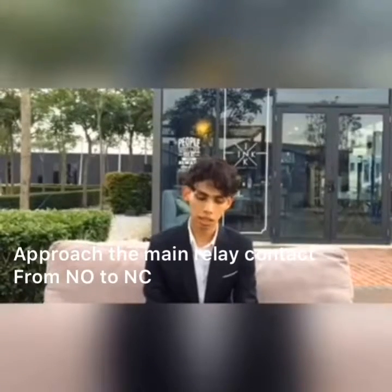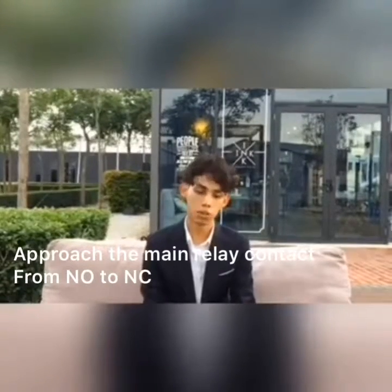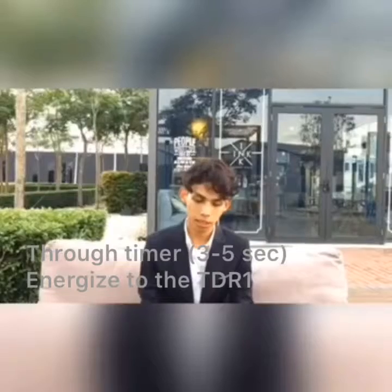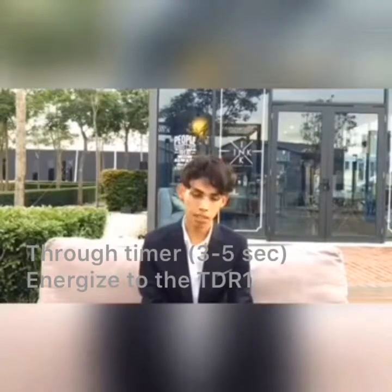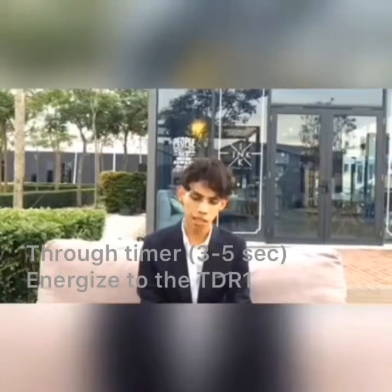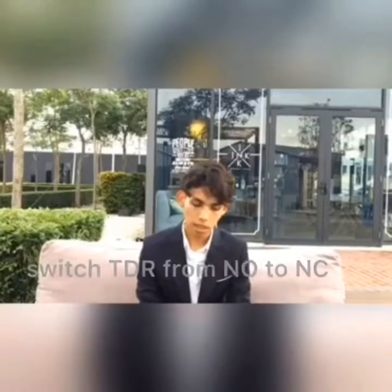The armature will move the main relay contact from normally open to normally closed because of the magnetic field produced while the coil is energized. The current continues to flow through the timer, which ranges about 3 to 5 seconds. Then it will energize TDR1. Next, the TDR1 switch, which is normally open, will close during the magnetic field operation.